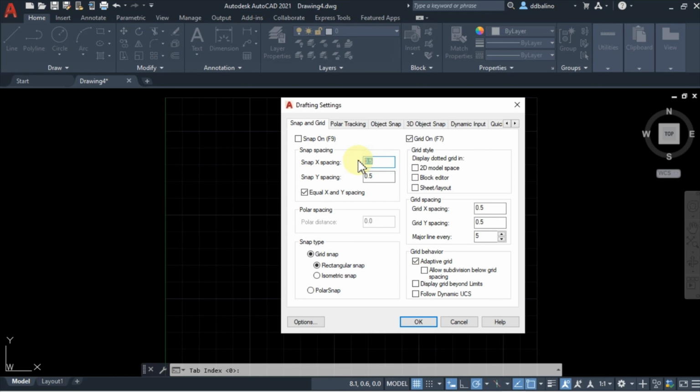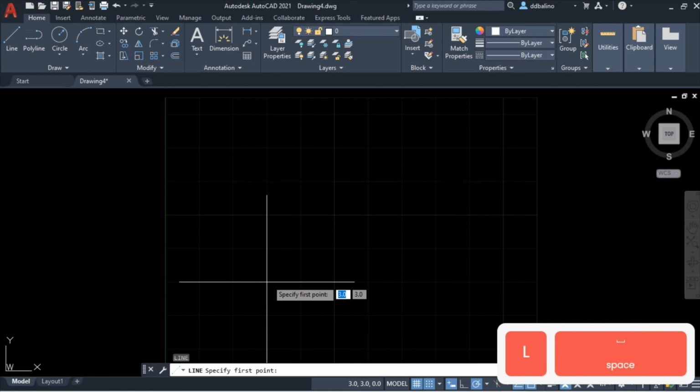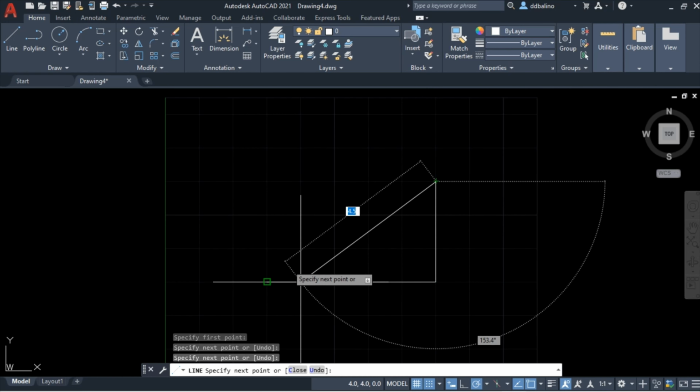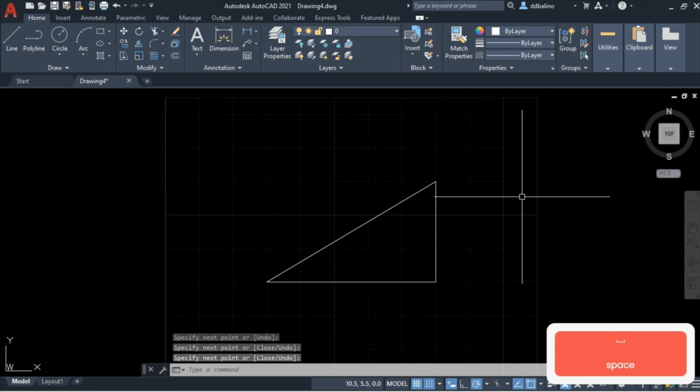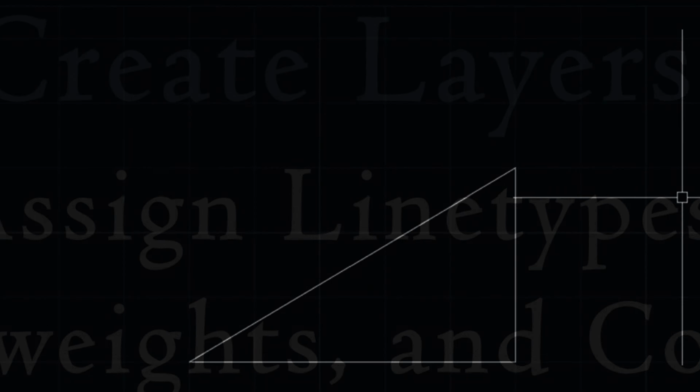The grid value setting is usually set equal to or proportionally larger than that of the grid snap value. Grid should be set to a proportion that is easily visible and to some value representing a regular increment, such as 0.5, 1, 2, 5, 10, or 20. Setting the value to a proportion of grid snap gives a visual indication of the grid snap increment. If you are not using snap because only extremely small or irregular interval lengths are needed, you may want to turn grid off.